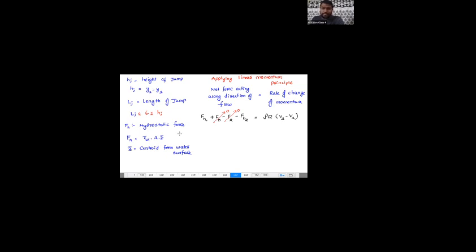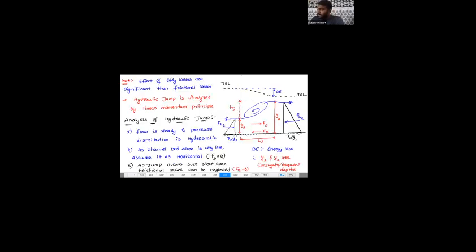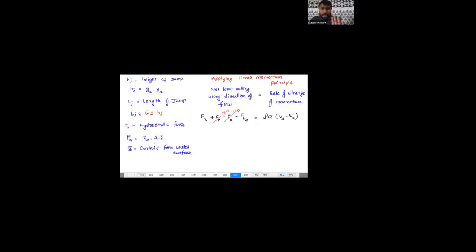So what is this hydrostatic force, sir? Hydrostatic force, generally, is the area of the pressure distribution. Here I am taking gamma W Y1 and gamma W Y2. Wait for that moment. This is the normal definition, gamma W into A into Z bar. For the rectangle and for the triangle, wait for that moment. Okay. Now, please substitute over here: gamma W into A1 Z1 bar minus gamma W into A2 Z2 bar.